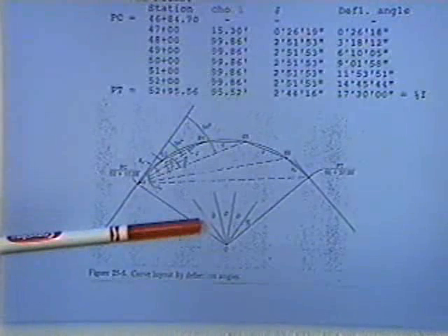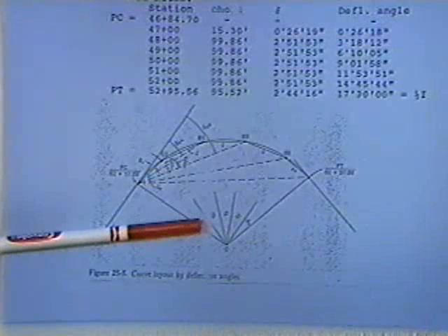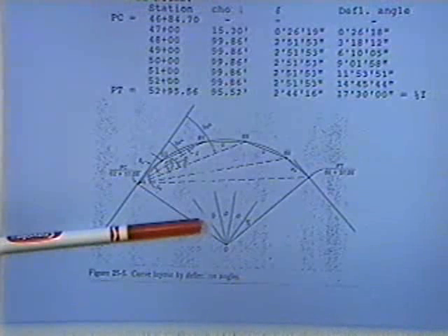Okay. So really, the only change that you would do for a design problem is that design problems typically give you the speed you want the roadway designed at, and you go to a table and look up what degree of curve you can use for that particular speed.